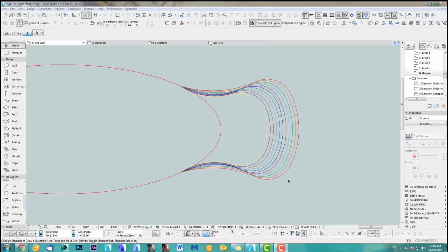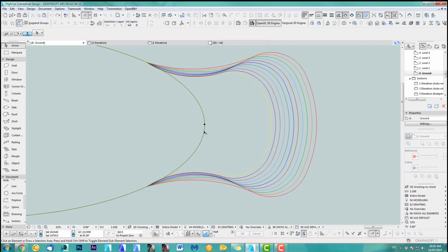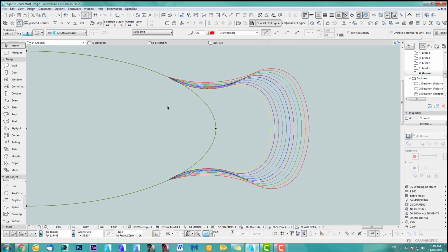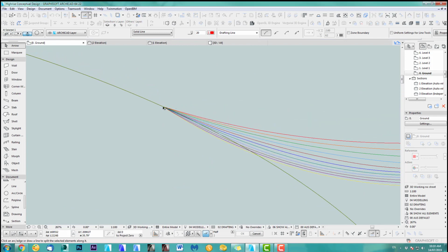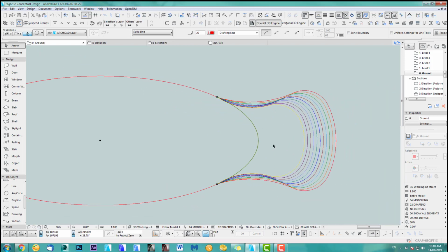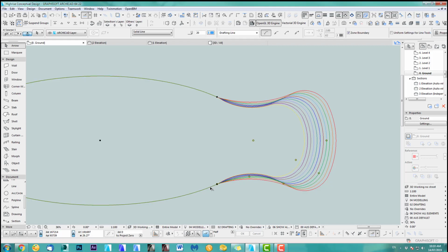So for the purpose of this tutorial, I added colors to my setbacks. It's easier to follow. And one more thing, before I start copying stuff around, I really want to cut this off. So you select this and we split this, and it has to end here. There you go. Tick. So you go straight and you're going to go that way. And we delete. We don't need this. So they're all nicely connected now.